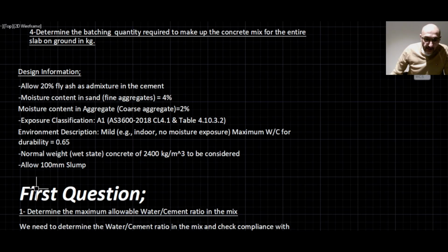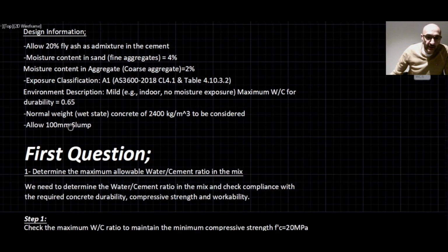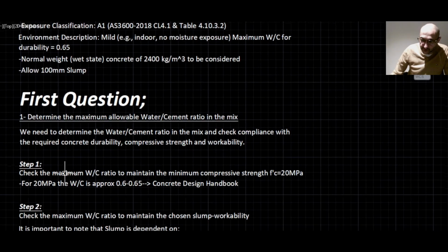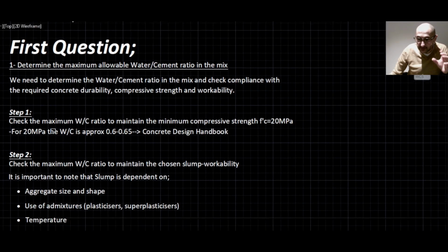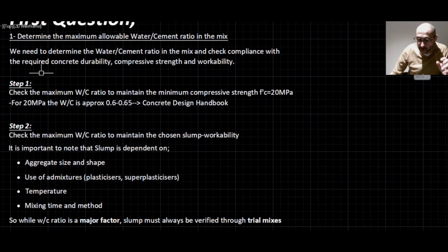Now let's address the first question. Number 1, determine the maximum allowable water cement ratio to be used in the mix. Again, like I said before, we need to check compliance with the required concrete strength, durability, and workability. The first step, check the maximum water cement ratio to maintain the minimum compressive stress of 20 MPa.